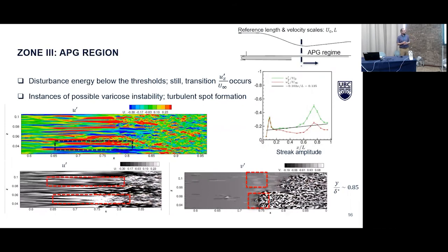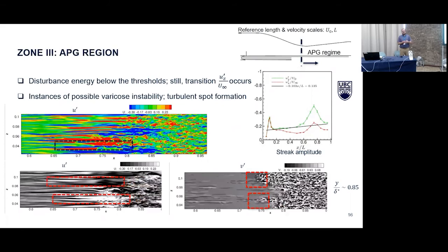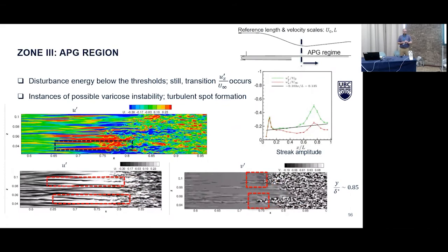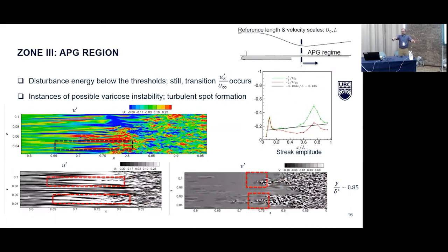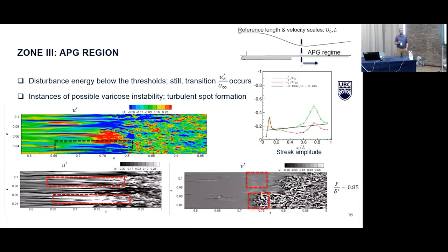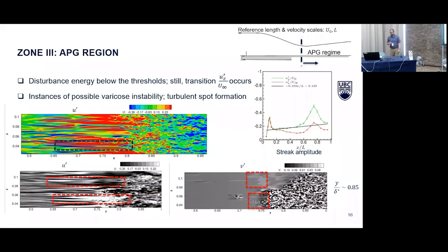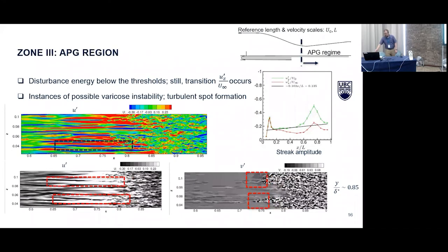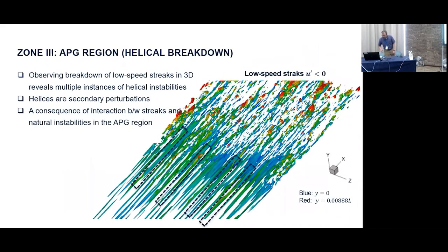Because here we have the streaks growing, getting stuck. It's like we let them grow for a little while, they now stop. And then as they enter into the adverse pressure gradient region, okay, now have your party, and then they behave in a manner very similar to the bypass transition under free stream turbulence. Okay, so maybe a couple of very specific comments.